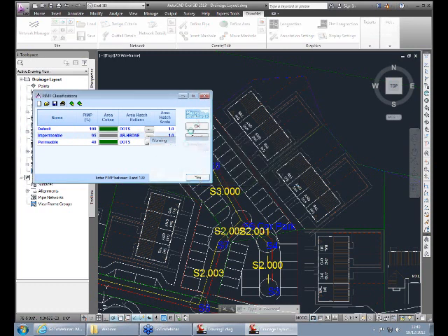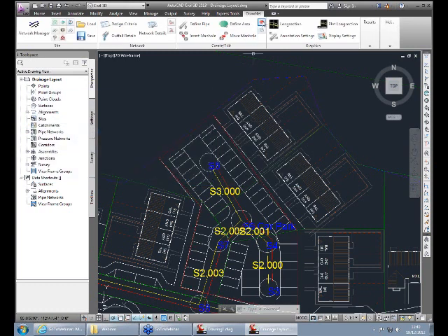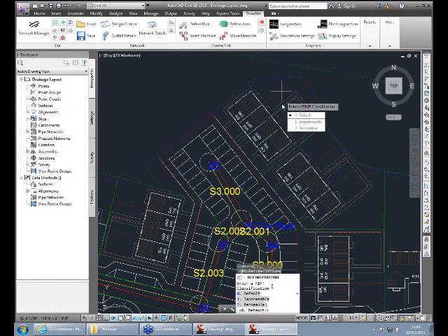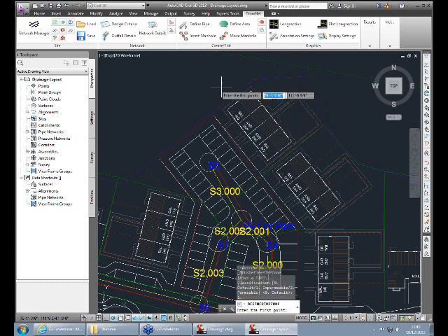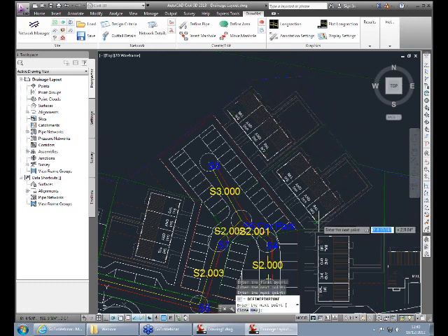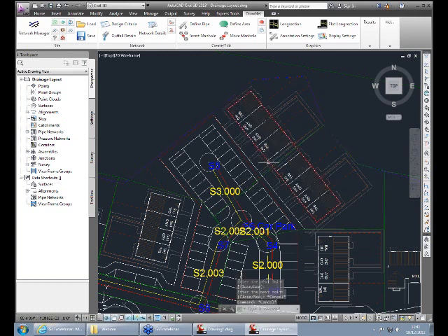So I go yes on the form. Now I can specify my PIMP zones. So to start off, I'll do an impermeable area. So select impermeable, we can snap on the drawing. I draw around the house roofs at this location, and that will be 95% runoff or 95% impermeable for this roof area here. So you can see the dotted line which surrounds it.